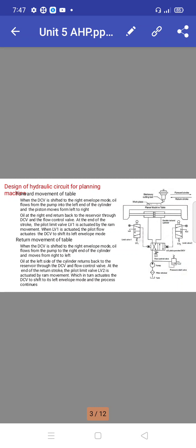In the forward stroke, it removes material or executes some work. In the return stroke, it is idle, so it should come back in a very fast, rapid manner to reduce the time taken to return to the original position. The rapid return stroke reduces the total time to complete the task specified to the machine.